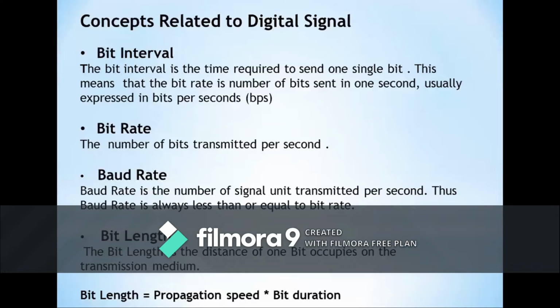When binary bits are transmitted as an electrical signal with two levels, 0 and 1, the bit rate and the modulation rate, that is baud rate, are the same. For two level signals, the bit rate and baud rate are equal. If each level is represented by a combination of two bits, that is 00 or 01, the bit rate is therefore not equal to the baud rate in some cases.